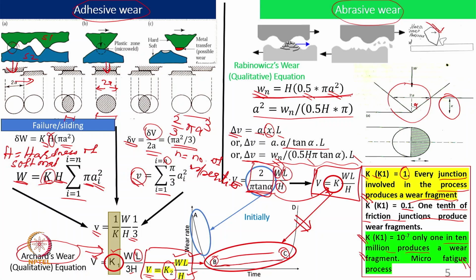However, in the dry case, the wear coefficient will be on the higher side, and in the lubricated case the wear coefficient will be much lower. We do not know this exactly, but many times people use this kind of relation. They do experiments, and then whatever constant k comes out, they try to use it for simulation purposes. So this is an important aspect to consider.